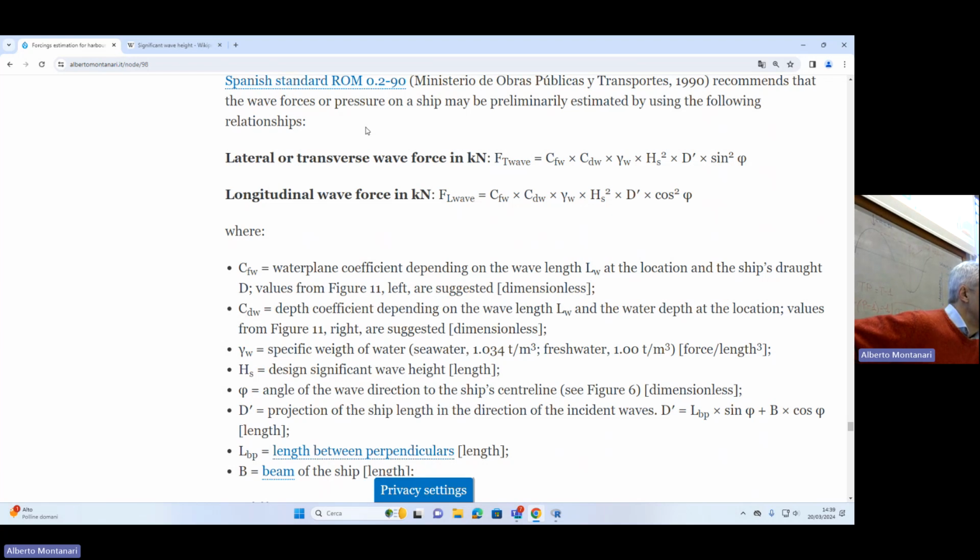You have sediment transport close to the shoreline because it's after breaking. When the waves break, the movement of energy is transformed into a movement of mass, and therefore you have drag. Sediment transport is originated by drag because it's mass movement. But in open ocean, as you said, it's just up and down, and there is no movement along.